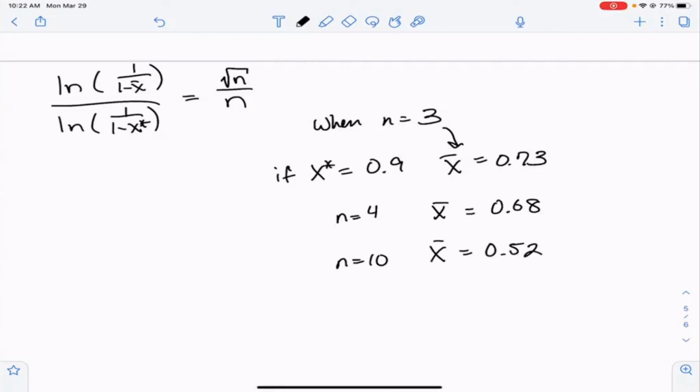And the reason this is happening is because as you split the reactor into different sections, the volumetric flow rate is going down. When that happens, the velocity goes down. So the diffusion layer thickness increases, and that leads to slower mass transfer coefficients, and that leads to lower conversion.